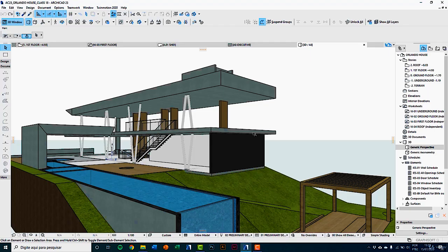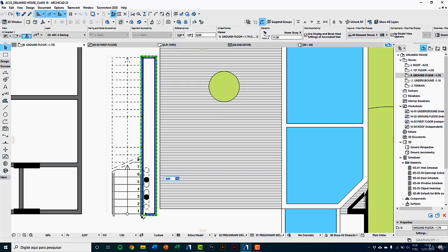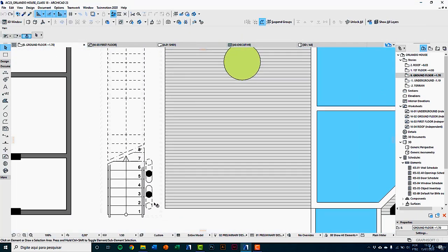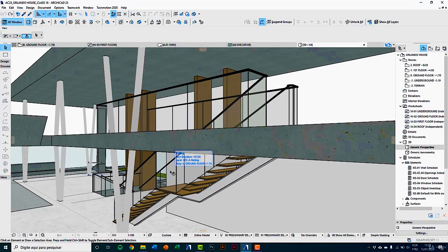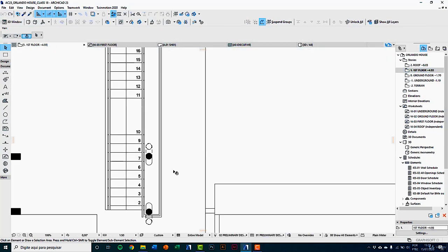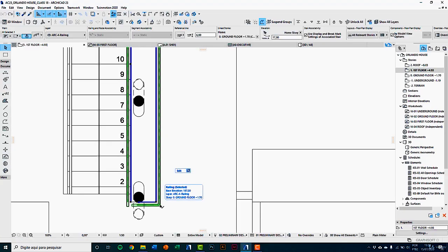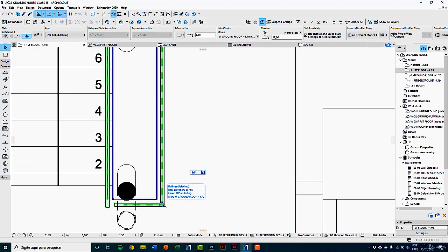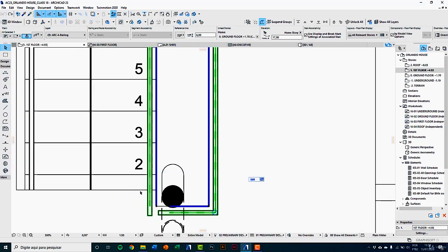So first we see that railings don't have a correct representation in floor plan. You can see here on first floor and ground floor. And looking in 3D, a very difficult thing is that railings start at ground floor in this case and end at the first floor. So looking in first floor, we have this situation. We see the railing needing to be above the slab in the draw order view, but this edge going downstairs should be below the slab.